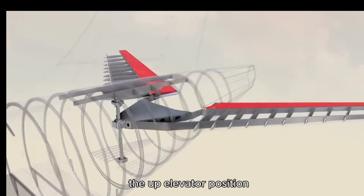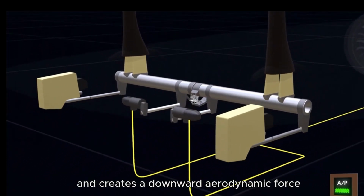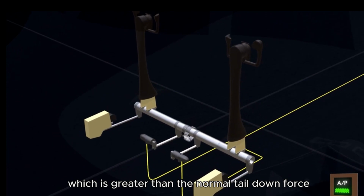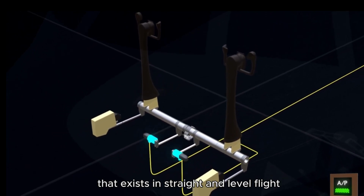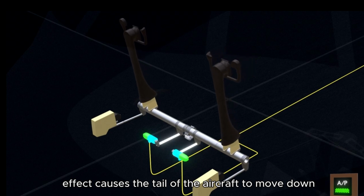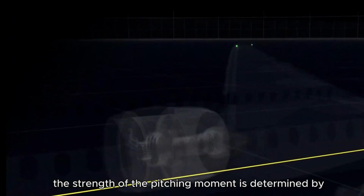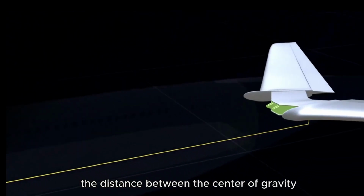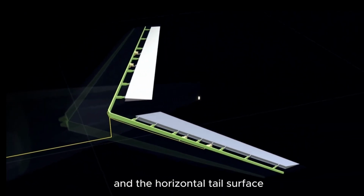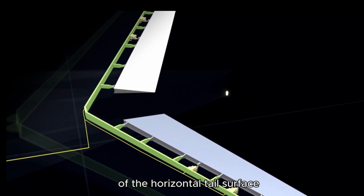The up elevator position decreases the camber of the elevator and creates a downward aerodynamic force, which is greater than the normal tail-down force that exists in straight and level flight. The overall effect causes the tail of the aircraft to move down and the nose to pitch up. The pitching moment occurs about the center of gravity. The strength of the pitching moment is determined by the distance between the center of gravity and the horizontal tail surface, as well as by the aerodynamic effectiveness of the horizontal tail surface.